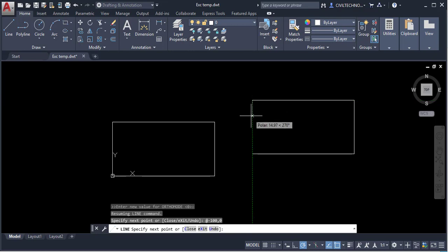Now we have to just give a value of this point. Now here in this case I will just enter at the rate symbol and x 0 and y minus 50. Okay, and I will hit enter. Now you can see here it is going to close. So this was the relative coordinate system in which we can just draw anything or in any position. So I hope you understand both of these Cartesian and relative coordinate systems.